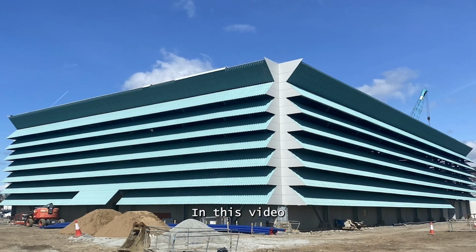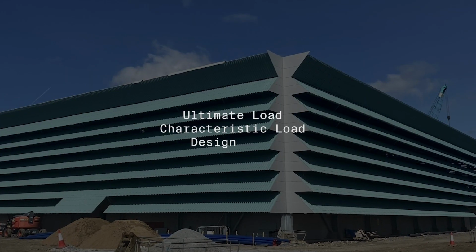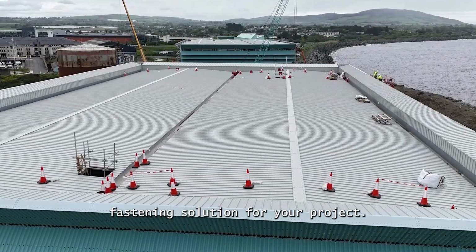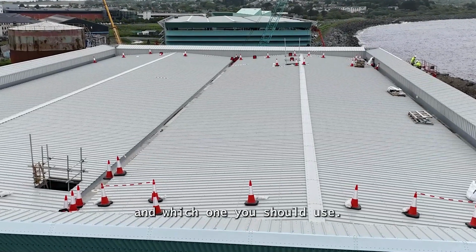Characteristic and design loads explained. In this video, we are looking at three important terms: ultimate load, characteristic load, and design load. These might sound technical, but they're designed to make sure that you get the correct fastening solution for your project. So, here's what they really mean, what the differences are, and which one you should use.